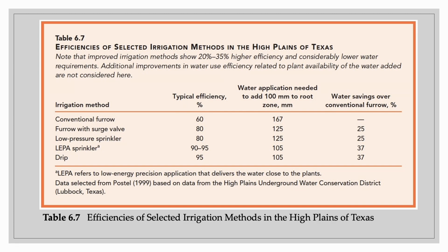All right, so wrapping this up, some of the things to be aware of are the different irrigation methods. In the Mississippi Delta, you've got probably a 1 mile field that has been graded, and it'd be very difficult to apply water to those row crops over a mile distance. But if you have a conventional furrow, that water will travel down and out the end, and you can get about 60% efficiency.